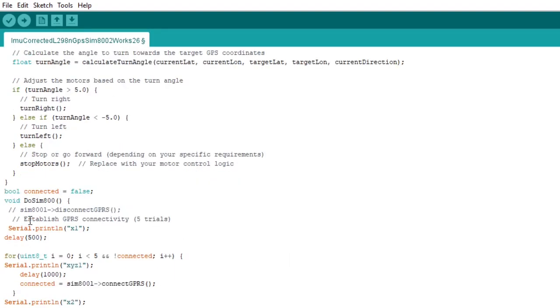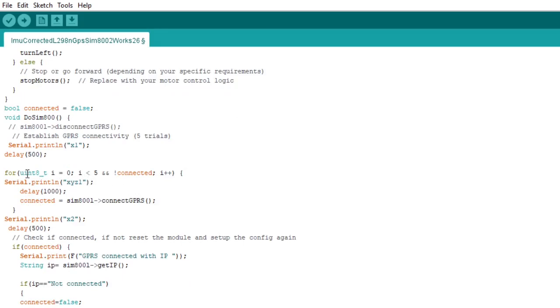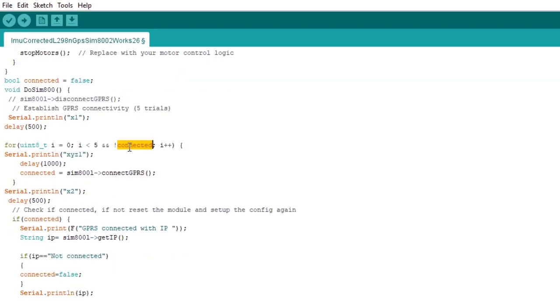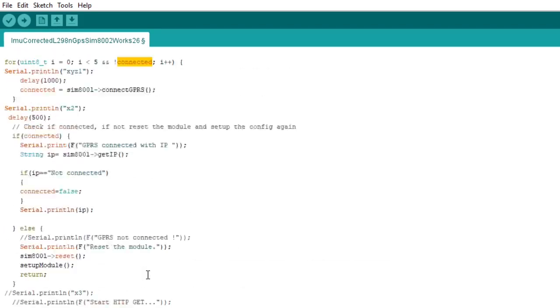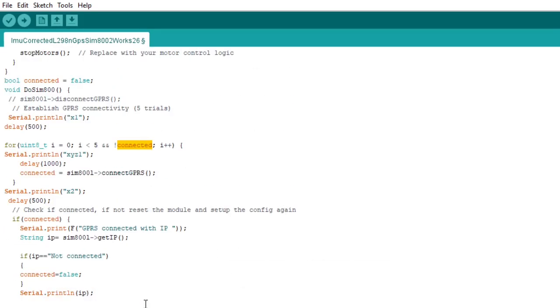And then we've got the SIM800, where when we're connecting, every time we'll try to connect to the server to see if we can connect, if it's not marked as connected already. There are some reasons why you'd want to go with this approach, because some IP addresses, you put it this way, you've got problems with them when you try to connect to networks. So what will happen here is the code will run, it will connect to the internet, it will get an IP address, it will try to connect to the server. If it fails, it will disconnect, and it will keep a connection, and if next time it fails, it will disconnect and restart the connection.